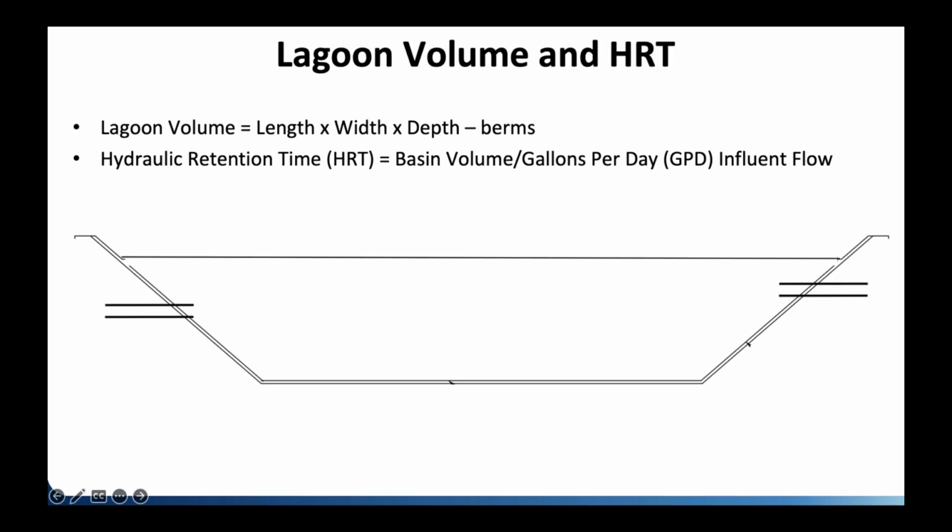So now you've figured out the flow. Another really important metric is looking at the lagoon volume and how that relates to what's called hydraulic retention time. Hydraulic retention time is, in layman's terms, the amount of time that water nominally sits in your lagoon. So the average gallon of water coming into your lagoon will stay there for 3 days, 20 days, 25 days, 120 days, whatever that number is. That's your hydraulic retention time.